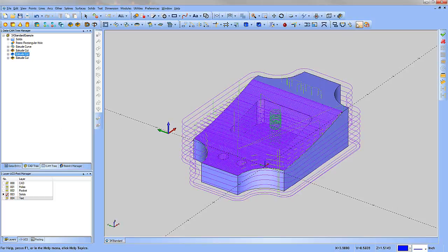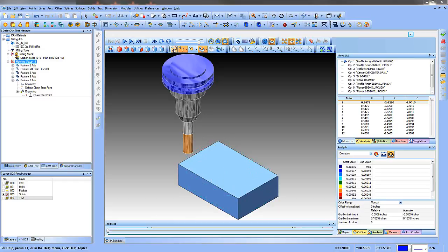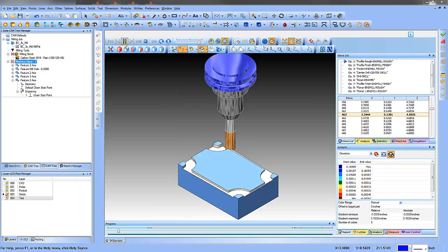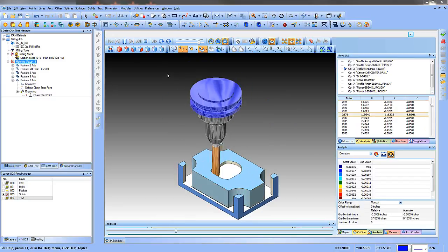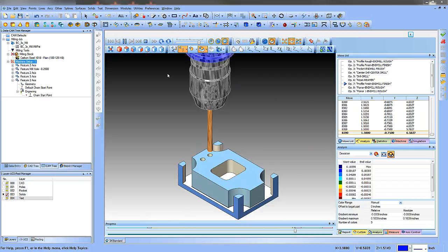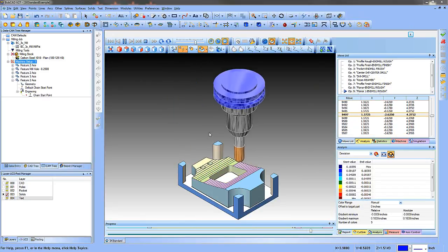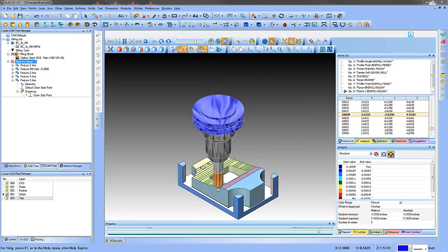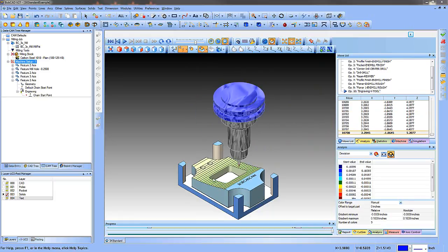And then we can go ahead and load up the simulation. And then turn off our toolpath and hit play. And just watch this whole thing rough out and get all cut out. So here's our pocket. And then we're just going to drill. Slow this down a little bit. And then we're coming in and finishing the whole part right here. And because we suppress that, it's not even looking at that pocket. It's just cruising right across it.